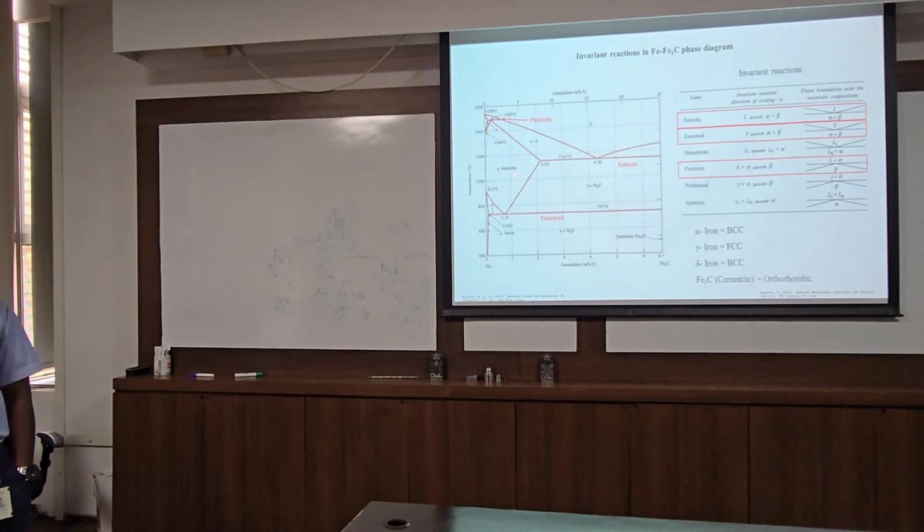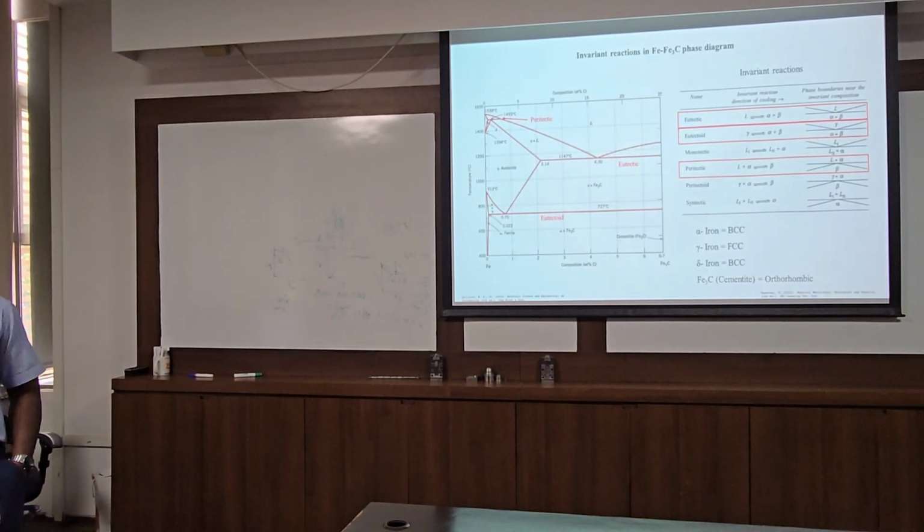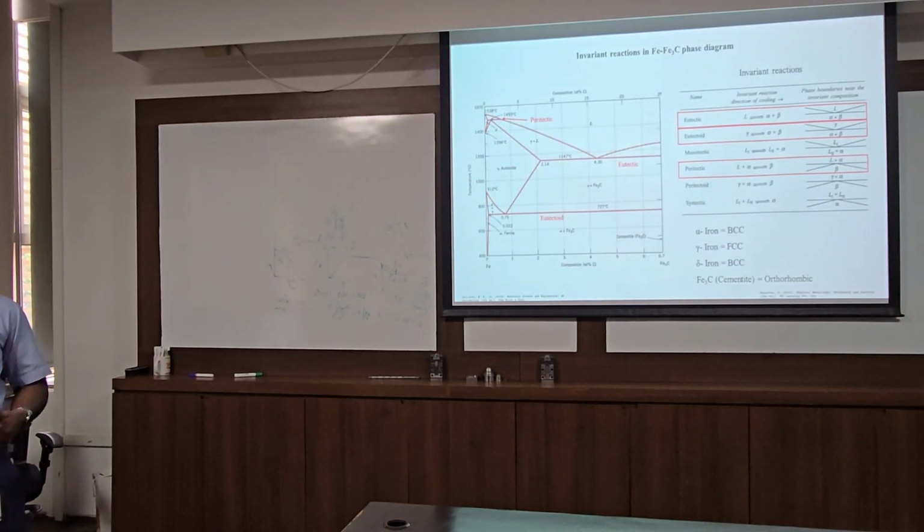But in steels, no application is there above 1000 degrees centigrade. Once it goes to 1000, it will become very soft, so there is no structural stability. Alpha will become soft at that temperature. Alpha will transform entirely to a stable single phase. But anyway, once you quench it, you get two phases again.